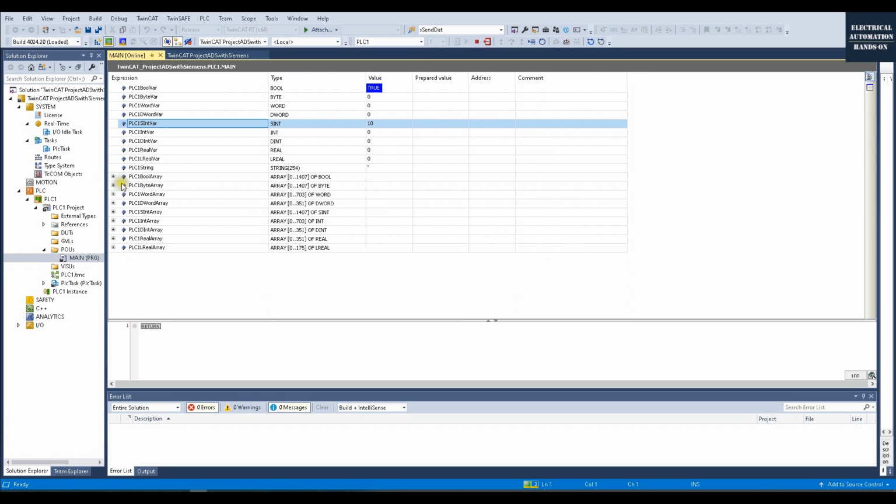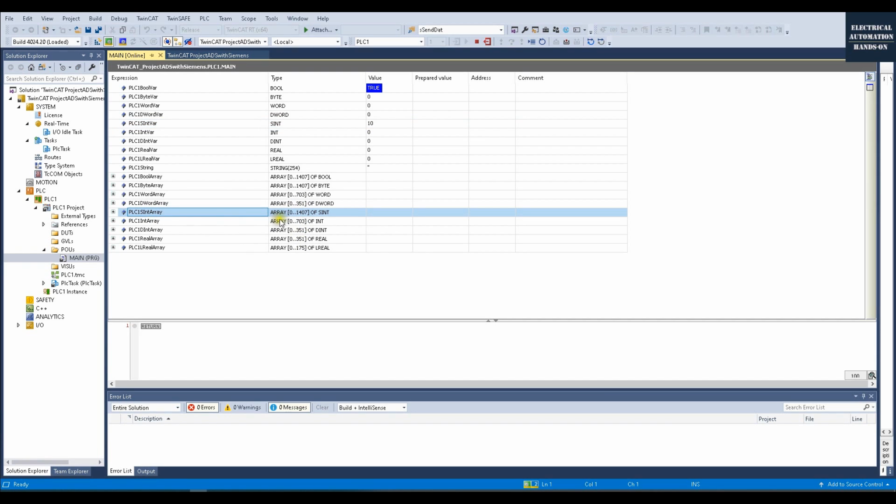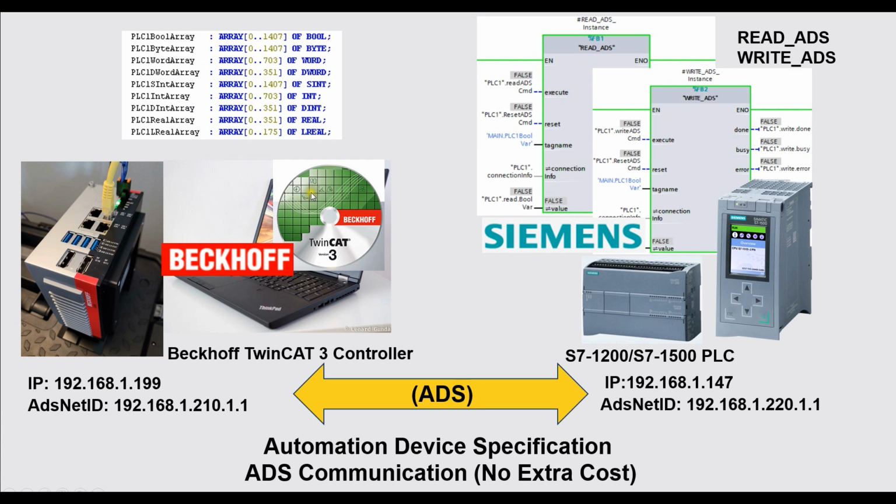So it has a lot of variables here. Basically, Siemens set this up as the maximum length of this protocol behind the ADS. We prepare everything with almost zero effort, because all those settings are the defaults from the TwinCAT3 project. Literally, we just copy all those variables prepared here. Now we just save it, and from now we can switch to the Siemens side. The Beckhoff side is done.